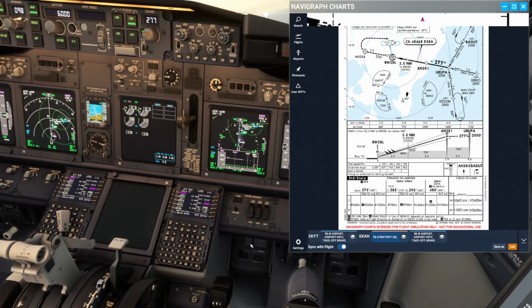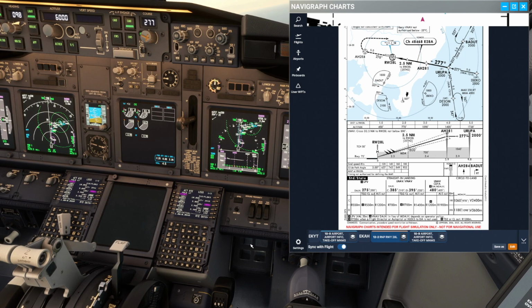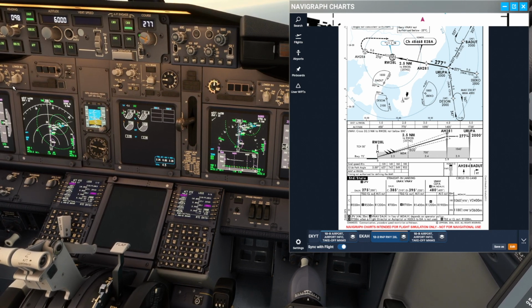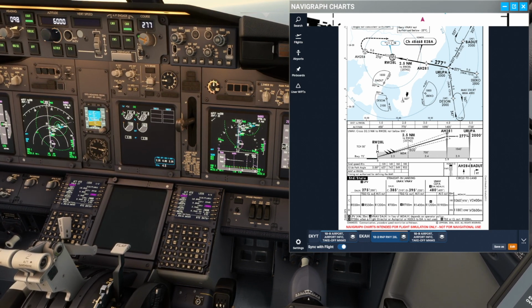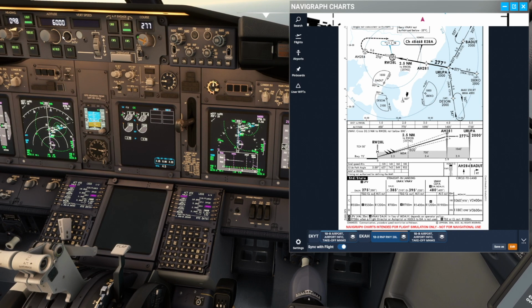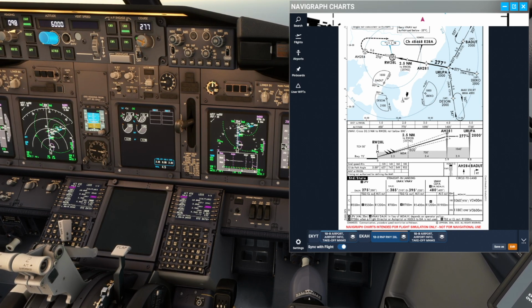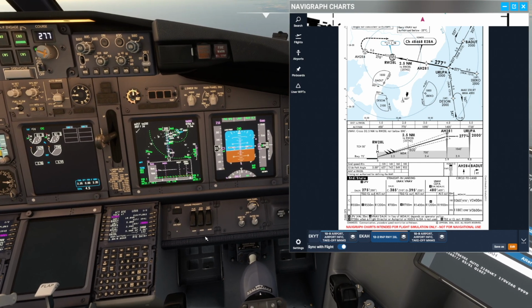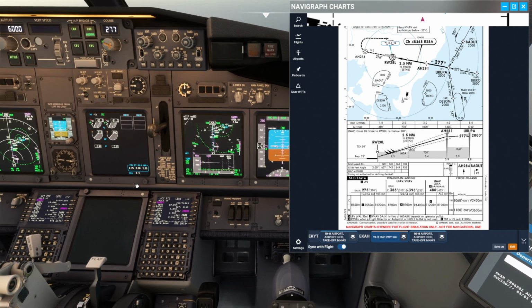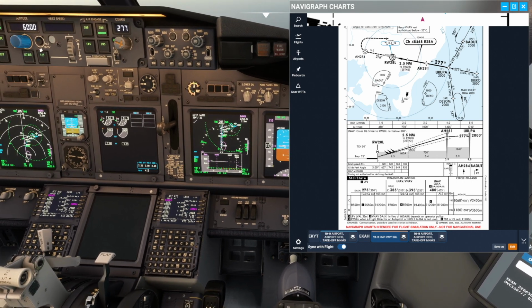And that's the thing with certain criteria in VNAV when flying these approaches. You can reset the altitude. So this is the only exception where VNAV is going to bust the selected MCP altitude. If you do this correctly, VNAV will take you all the way down to the minimum use height of the autopilot for this approach while staying in VNAV with a higher altitude selected. I'll show you on the approach, okay?